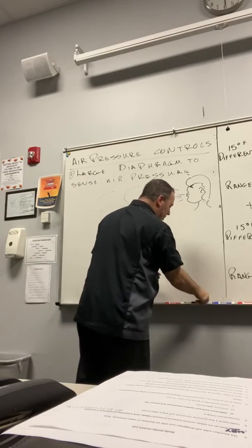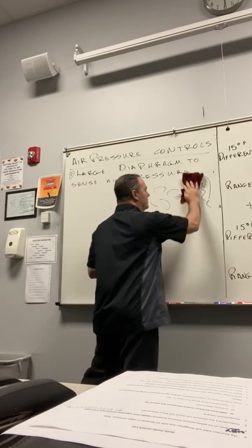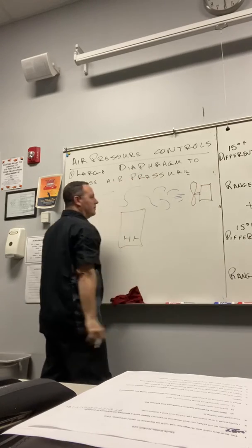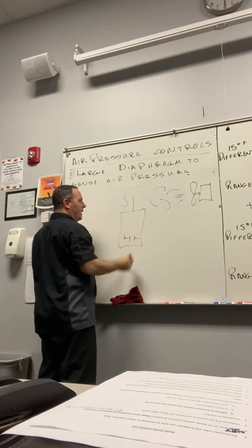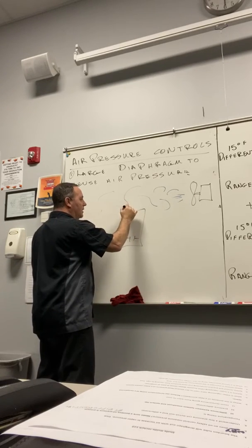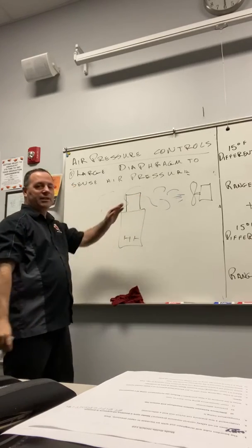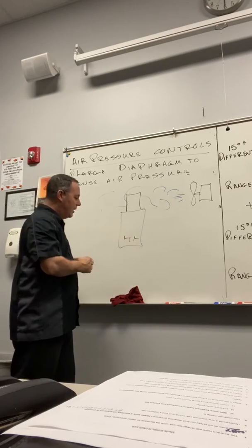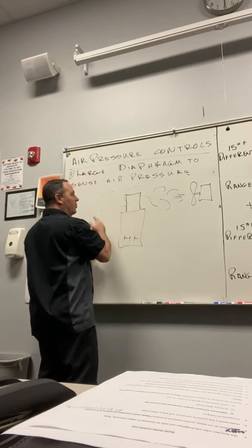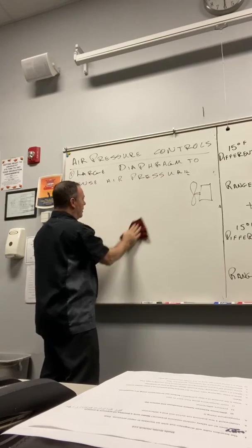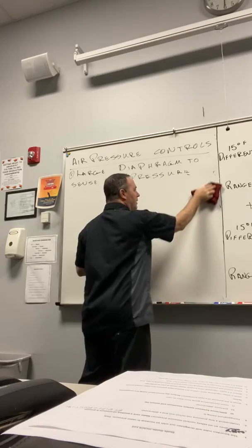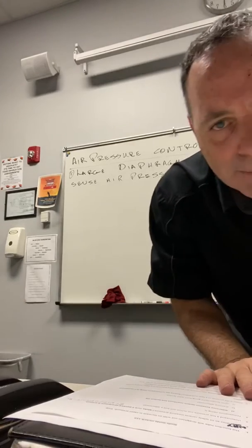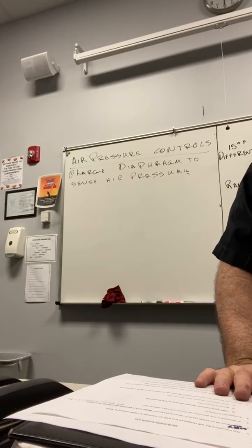And you wanted to measure air movement, what would you do? Would you put a little stick right here to measure it? Or would you put a large piece of metal like this that would blow over and open or close these contacts, depending on what you want it to do? Well, you're going to use a large diaphragm. So when the air hits it, it'll actually move. You don't want a toothpick right there, right? You want something that can actually sense the air. So in the picture, page 361 at the top, you can see that.